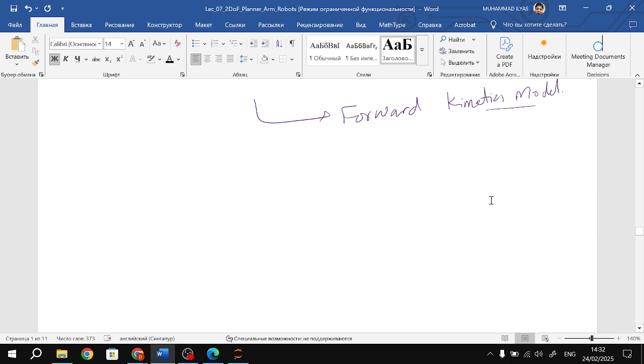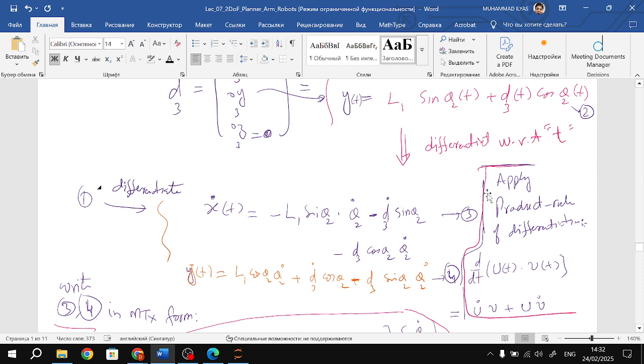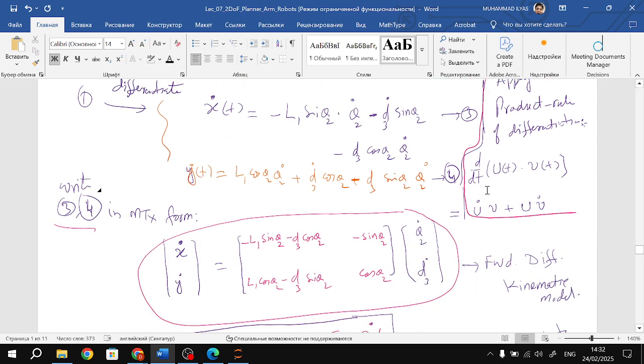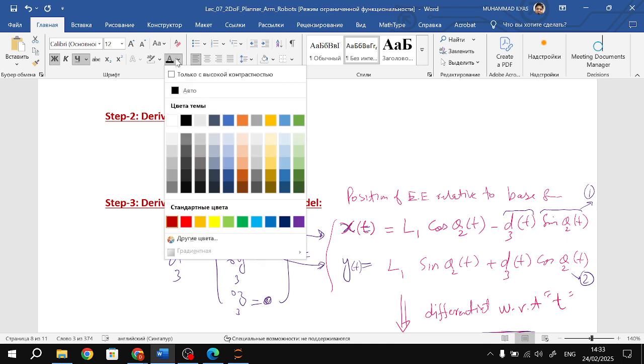We multiplied the HTMs and we got forward kinematics. When we multiplied the final HTM, the final HTM we get already, that is forward kinematic. When we derive the displacement, it is called differential forward kinematic. But here we only took the displacement part, right? We don't take the rotational part. Yes, only part of it.